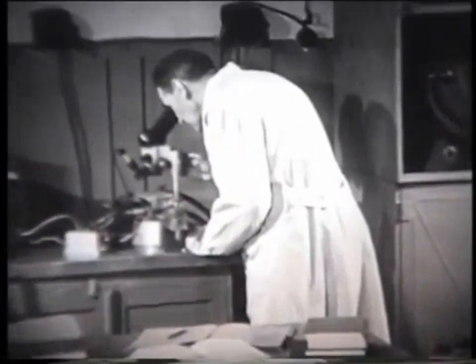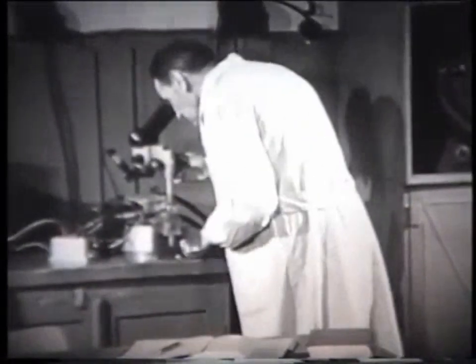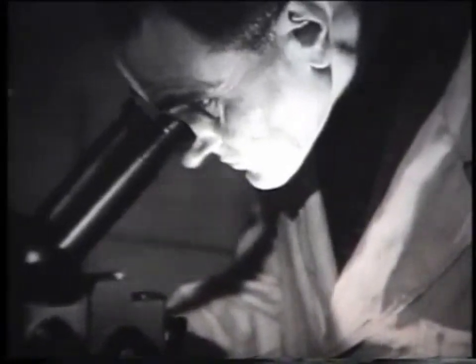Processing with high productivity cannot be carried out without effective removal of dissolution products from the inter-electrode gap. The method of removing dissolution products by electrolyte flow is widely used. This treatment is called anodic hydraulic. In this case, the solution is pumped at a pressure of 10 to 20 atmospheres at a speed of 3 to 20 meters per second.